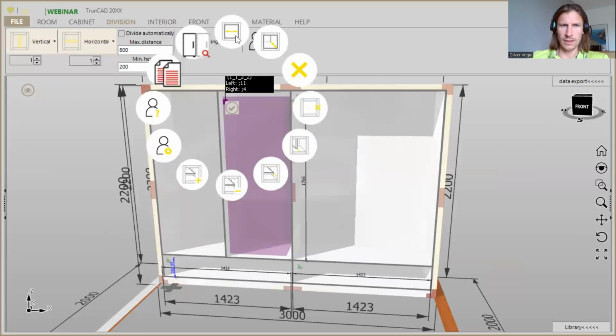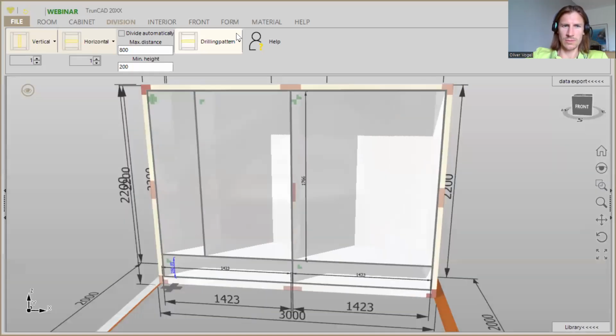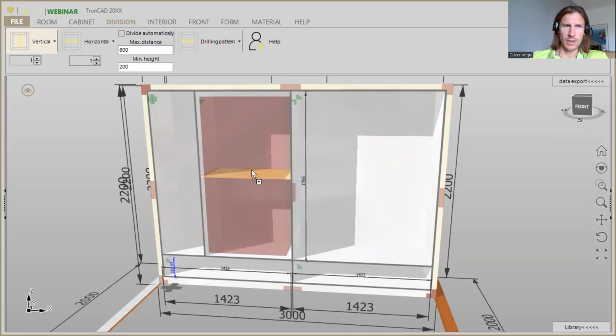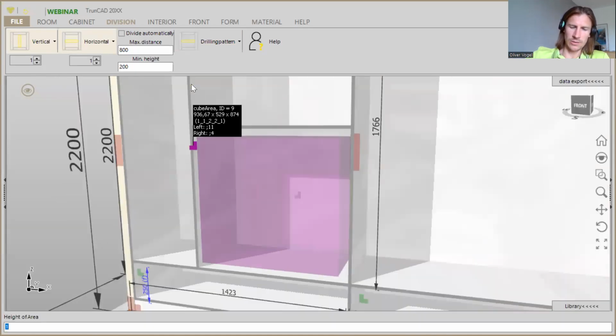and here we change the width, and here we are working with the number 2. That means the areas are related in relation 1 to 2 to each other. After we confirm it with enter, you see it. So then here in this bigger middle area, we add a horizontal again, and we are clicking here on the smart click and change the height to 150 and confirm it with enter.